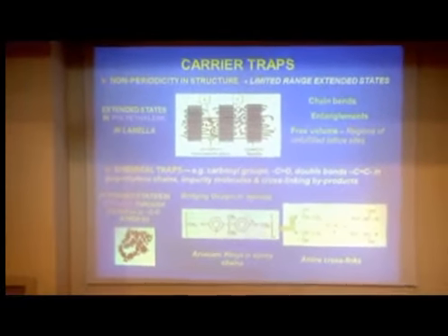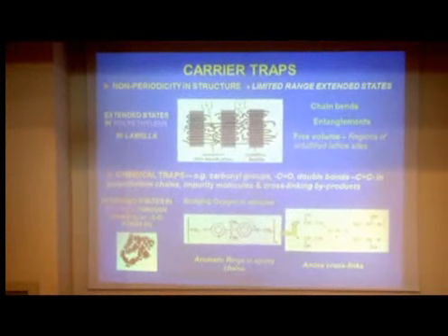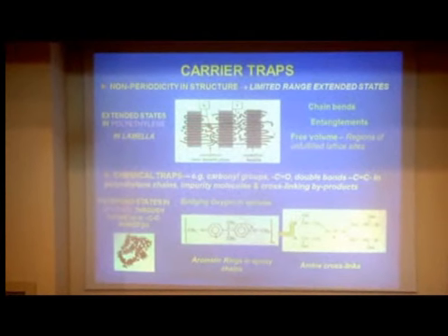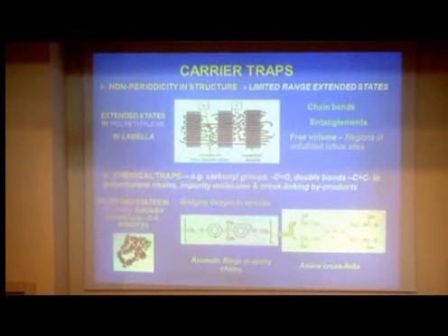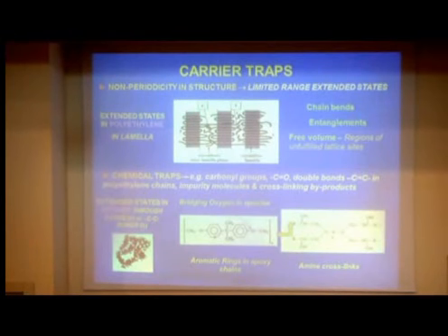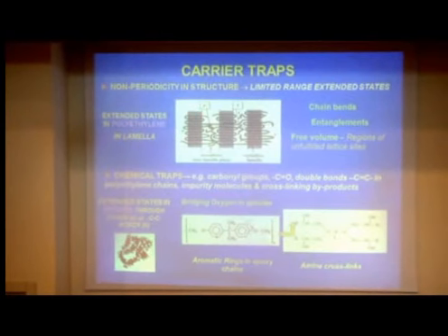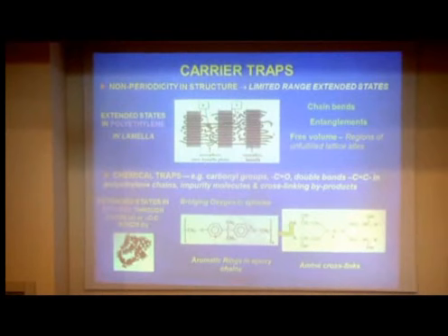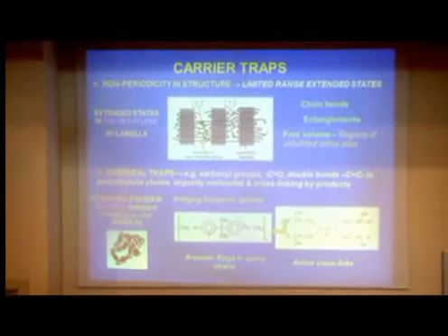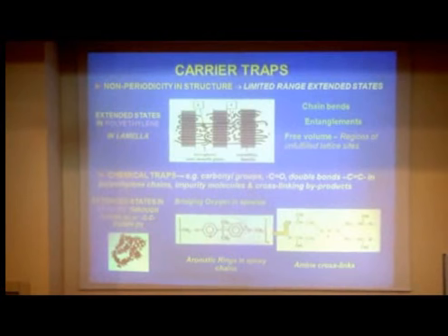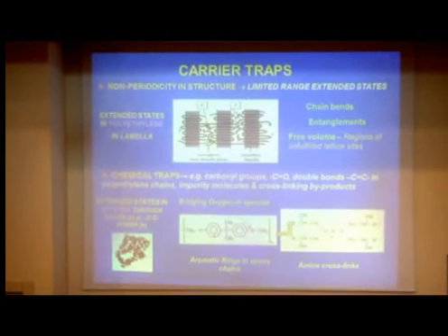If there was no field, there's no preferred direction. So electrons that get inside the lamella can move back and forth. It's quite happy to do that. So can the holes. They will move back and forth along chain sections. If there's a field, then the field imposes a preferred direction, and just as the electrons get trapped in the surface, the holes will reside on these surface bends. The trapping energy is quite small, but the field forces them to line up in that region.